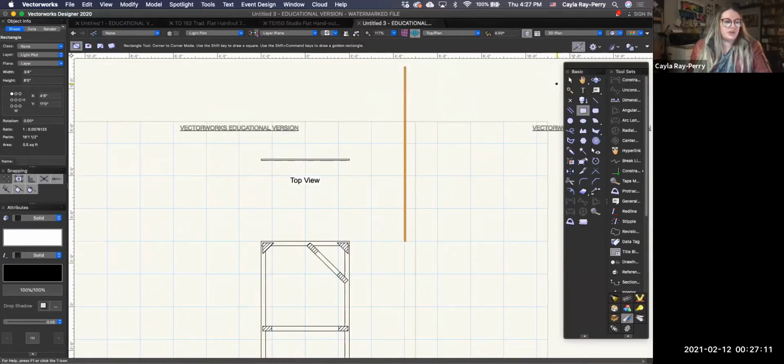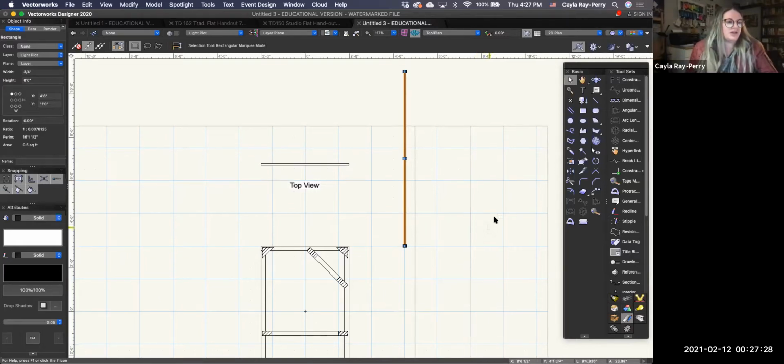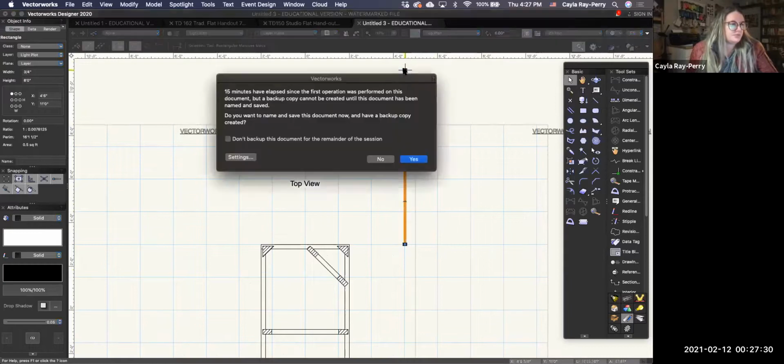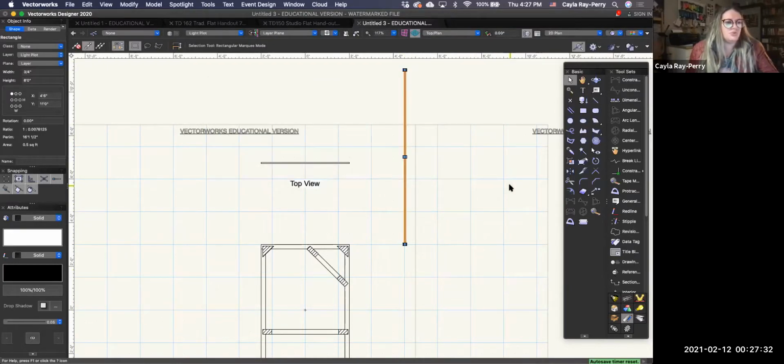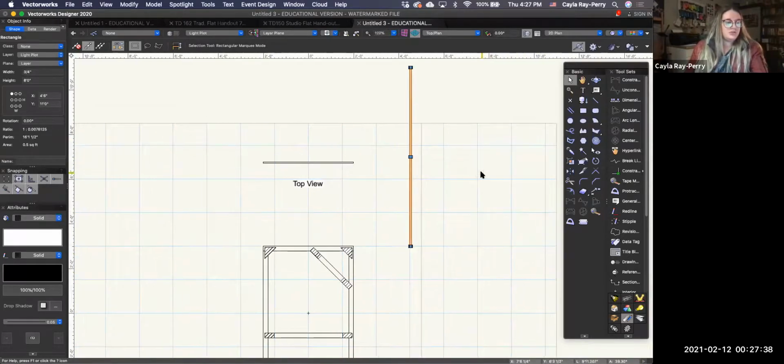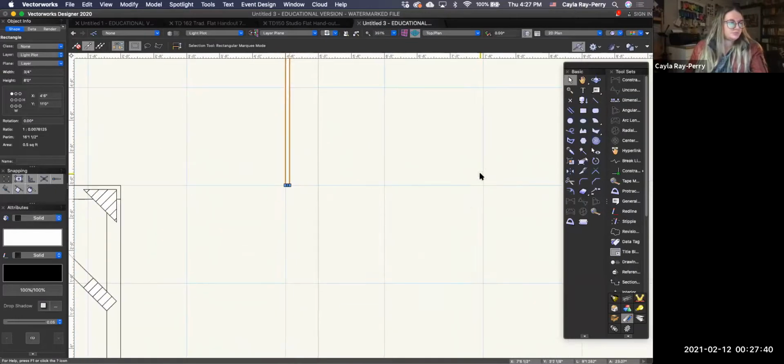Always does that. I always forget about. So it does read it in like minus. Whenever you make a point, it thinks of that as the center of your XY axis. So if you wanted to be 8 feet down from that, then you should type in minus 8 feet. I always forget to do that because I want to move it to where I want it on my paper anyway. So I think that's okay.